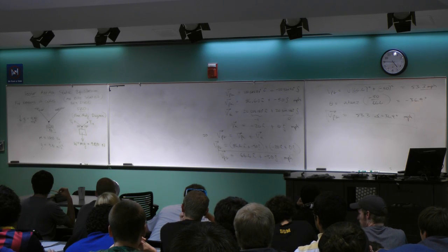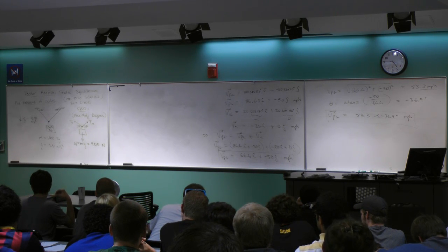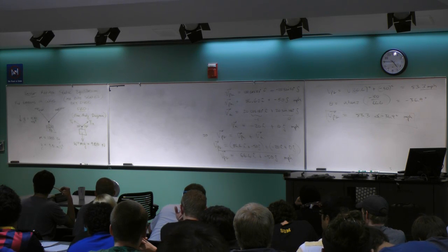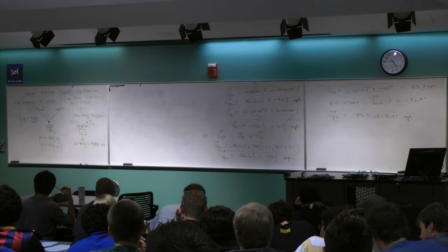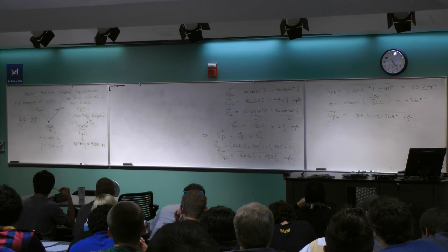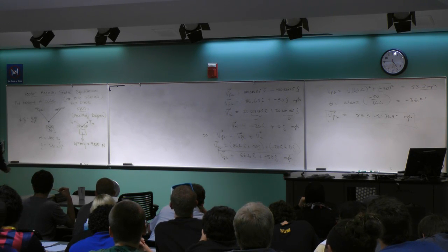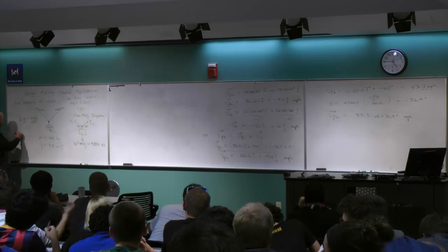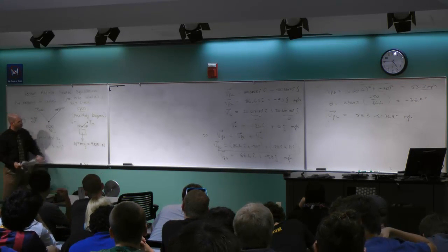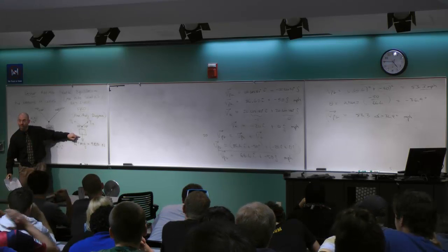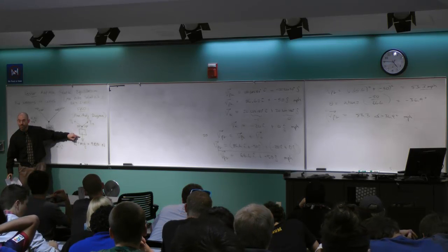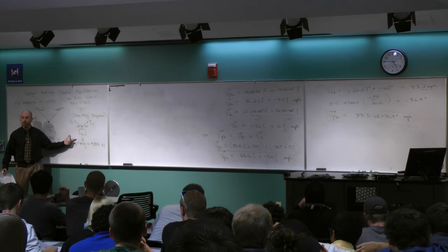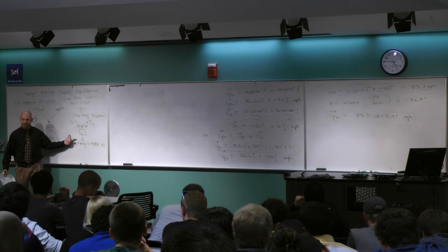Here's a general rule of thumb. If you draw a diagram that has forces indicated on it with arrows, the sign is built into which way you drew the arrow. If I want to represent this mathematically as a vector, using a standard XY system, then when I write this vector down, I will write it as a negative vector. But in this diagram, it's clear to me that this is down because I drew the arrow that way. Okay? So don't get too tight.